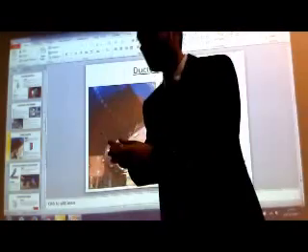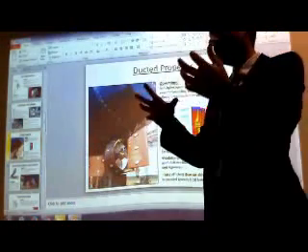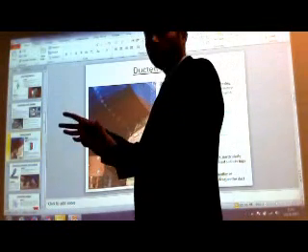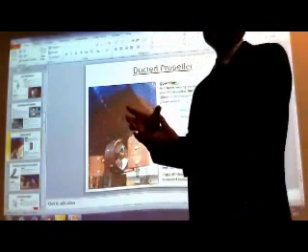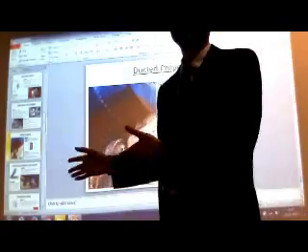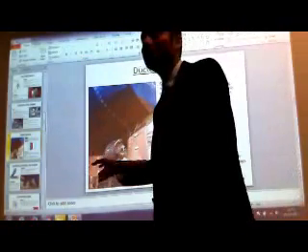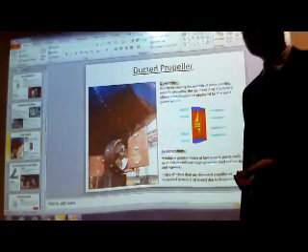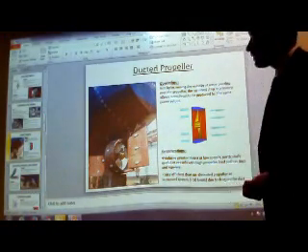If propeller wash is coming, it is creating water flow behind the ship. If you start changing the direction of this water flow, what will start happening? The vessel will start turning. It is one of your controllable factors. You can then steer the vessel. On this consideration, we don't use the rudder.